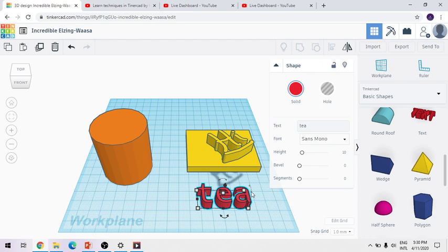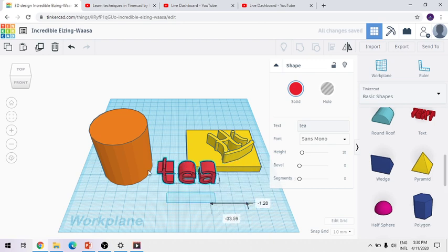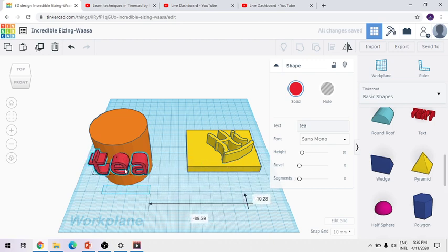direction. Okay, direction of rotation. So one shortcut is there: press shift while holding the rotation option. So this is one rotation option. Now I am pressing the shift key and I am rotating it 90 degrees. Okay, now I will move this object and I will place it on the cylinder.